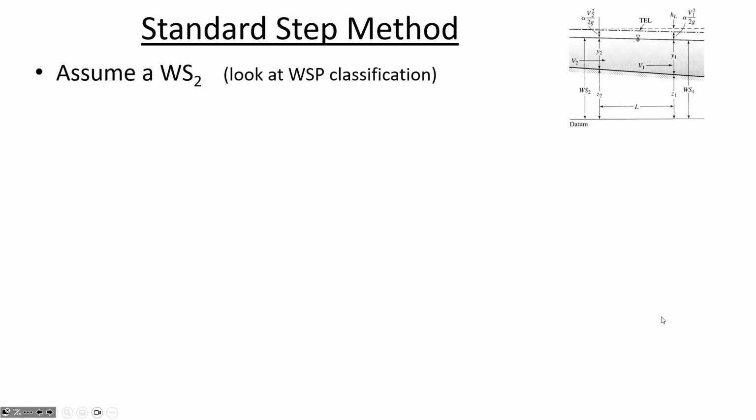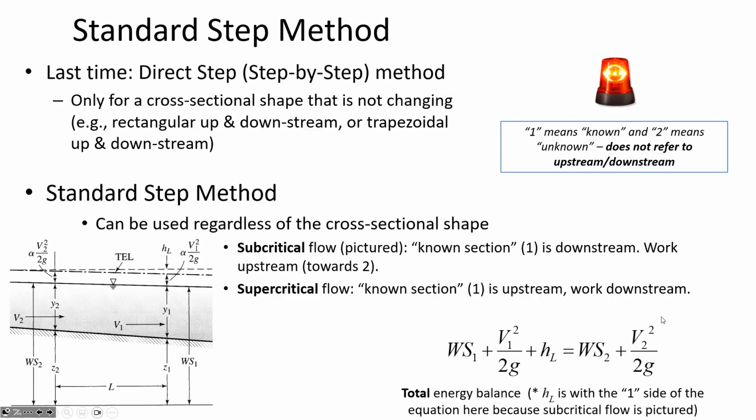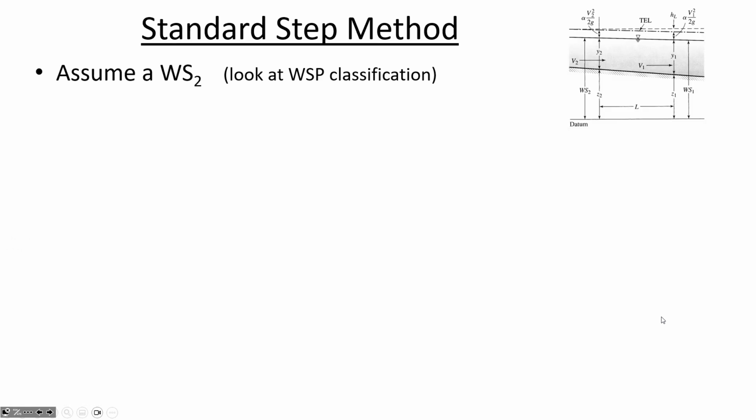So we're in a problem that we've been in before where we've got too many unknowns. Do you remember there have been several problems this semester where we had too many unknowns, and so we basically just made a guess. And we said, well, we'll start with a guess and then we'll see how things work out with that guess. And if it doesn't work out perfectly, then we'll change our guess and try and get closer to the solution by iteration and making adjustments. That's what we're going to do in the standard step method.